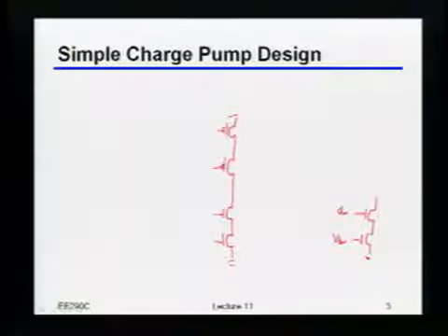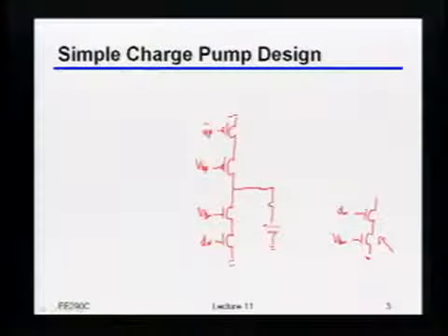In the one we drew last time, we put the switch on top of the device. Oftentimes you'll actually put the switch on the bottom of the device. As an example, this will be down, this will be up bar, this will be some bias voltage, and that will also be some bias voltage. And then of course this would be your actual charge pump output.